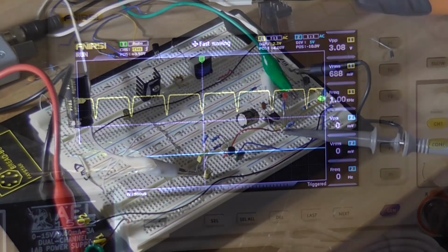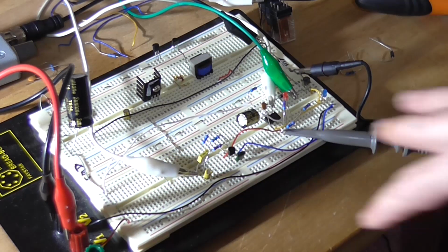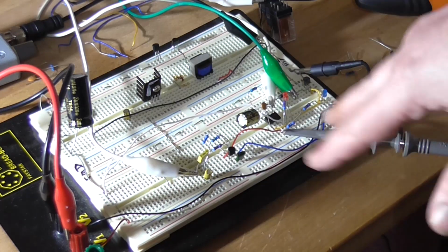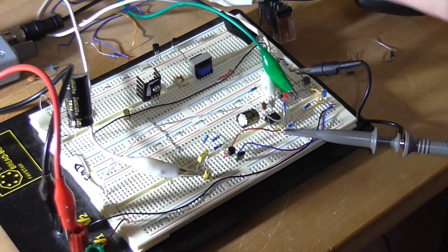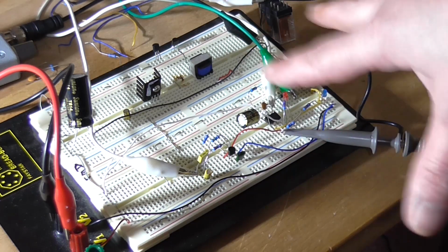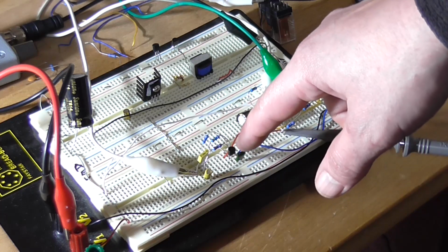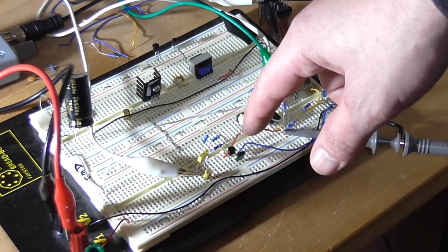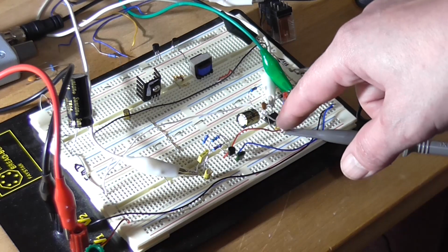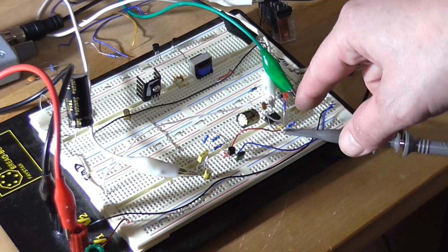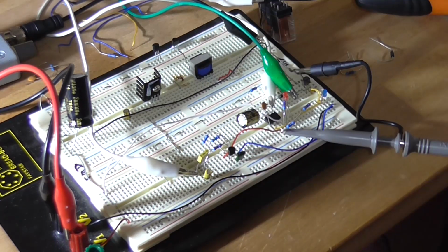a little bit better. Alrighty then, I've done some playing around off camera with some resistor values and stuff, and I've come up with a solution that makes this circuit more viable and functional. I've basically turned this first transistor into a Class A amplifier. That is, the 1K resistor that went between pin 2 and the positive rail, or the collector resistor of this transistor, is now a 100K.